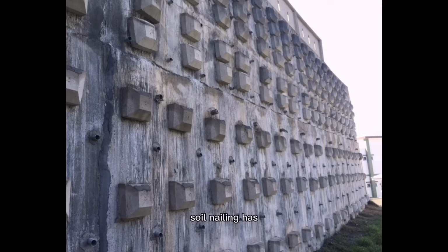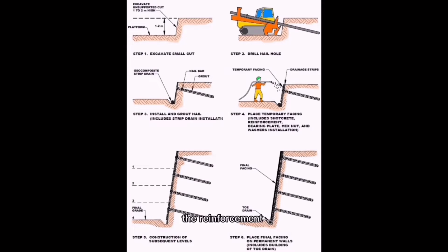Soil nailing has the effect of improving slope or excavation stability by increasing normal force on the shear plane and thus increasing shear resistance along the slip plane in friction soil. The reinforcement is installed horizontally or gently inclined, parallel to the direction of tensile strain in soil nailing, so that the maximum tensile force is developed.